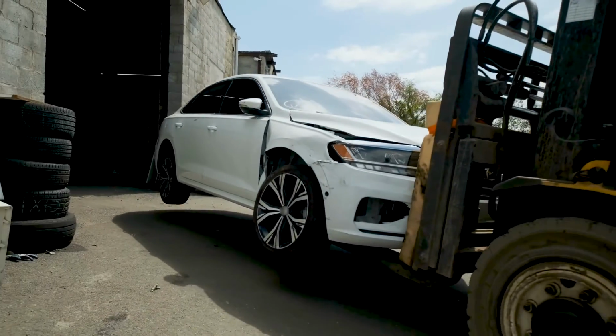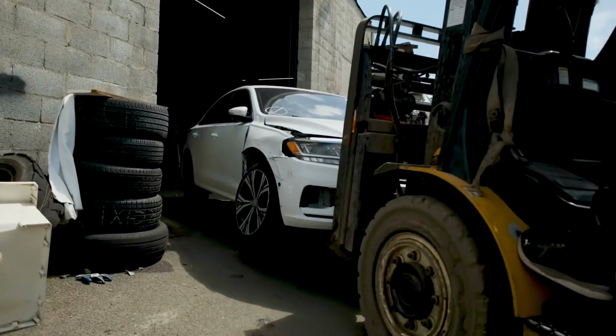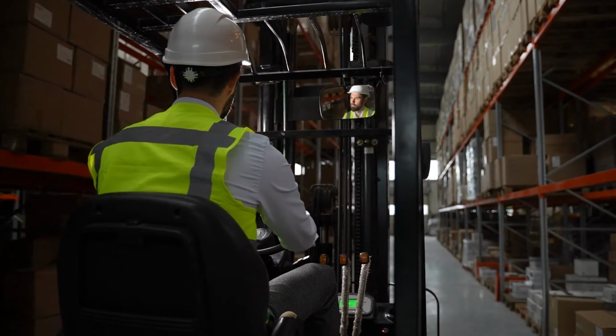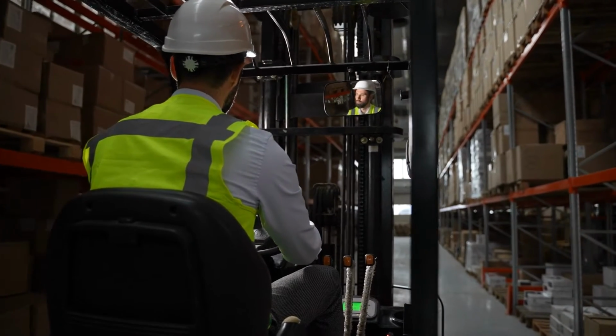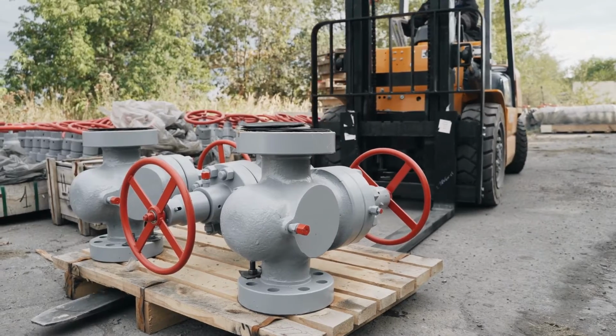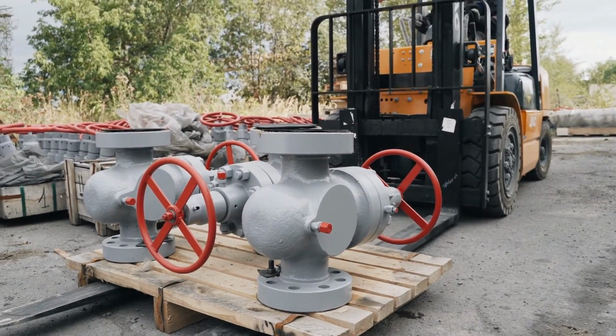With the front wheels of the forklift acting as the fulcrum and the forklift having its own initial weight, we can see how various load weights and distances can shift the center of gravity and lead to imbalance and a tip over. With a load weight of 0, the center of gravity remains squarely toward the forklift, and there's no risk of tip over. When the load weight exceeds the capacity of the forklift, then the center of gravity can shift beyond the front wheels, leading to the risk of a tip over. The same can happen if the load is placed too far from the front wheels. Now that we understand the basic principles of stability, we can take things a step further by introducing the concept of the stability triangle.